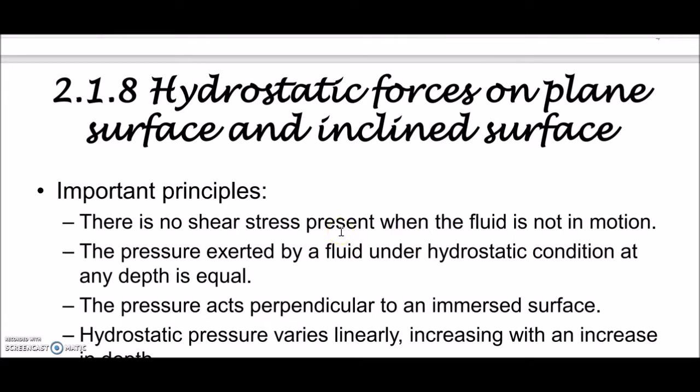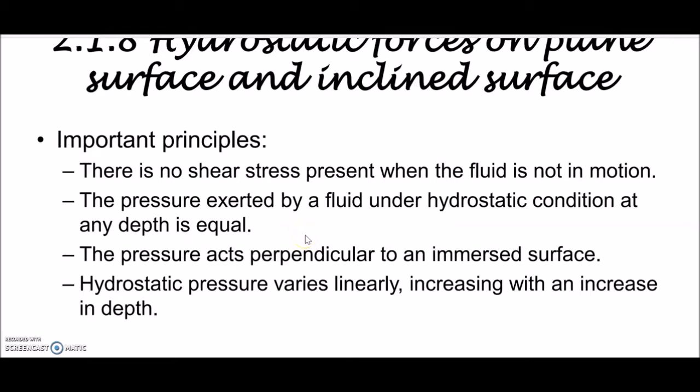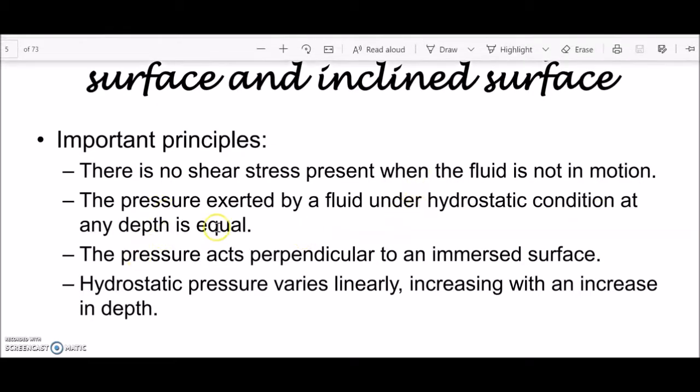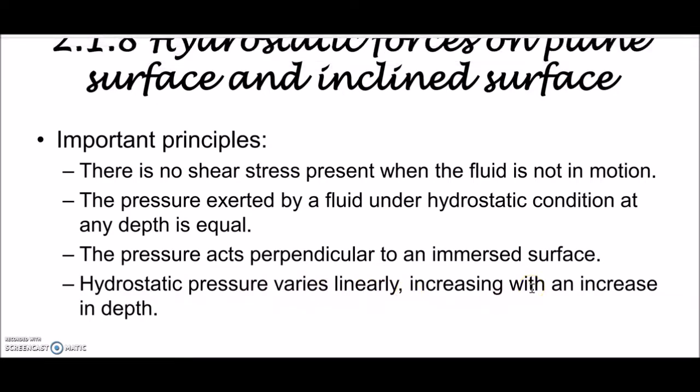It is when there is no movement of the fluid, so there is no shear stress present. The pressure exerted by a fluid under hydrostatic condition at any depth is equal. The pressure acts perpendicular to an immersed surface, and hydrostatic pressure varies linearly, increasing with an increase in depth.